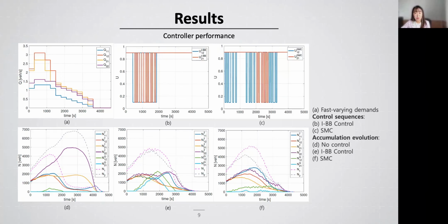For the sliding mode control case, it can be seen that the congested region becomes region 1, whereas it was region 2 in the no control case. This is because the sliding mode control tries to protect the more congested region 2. While perimeter control could ease the network congestion to some extent, the cordon queue sizes are higher when applying either the improved bound controller or sliding mode control, such that more vehicles suffer delay because of the perimeter controller.